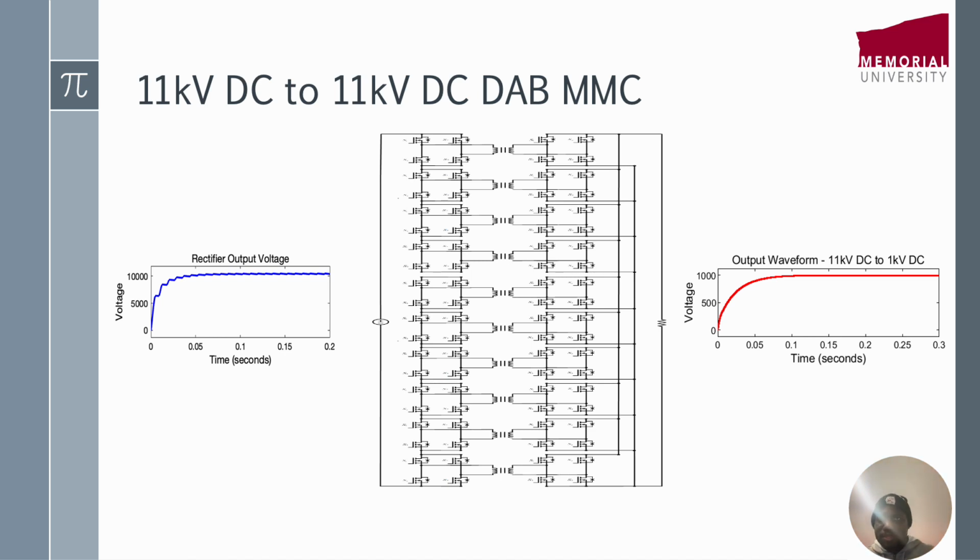Another point worth mentioning is that we want to ensure that the system operates in a stable manner. Then we must ensure that we don't parallel the input and parallel the output, or connect the input in series and the output in series. One side must be in series and one side must be in parallel.